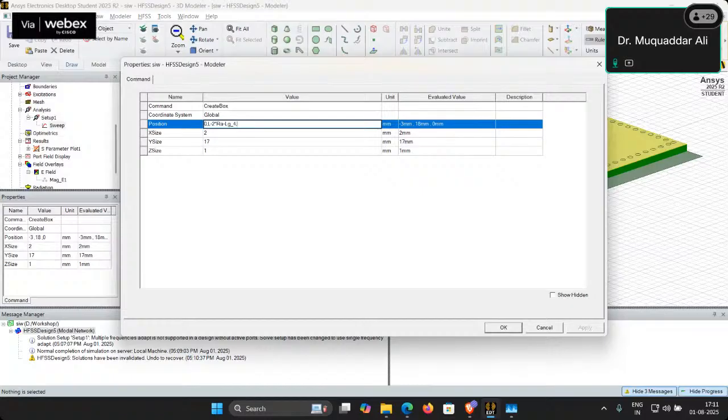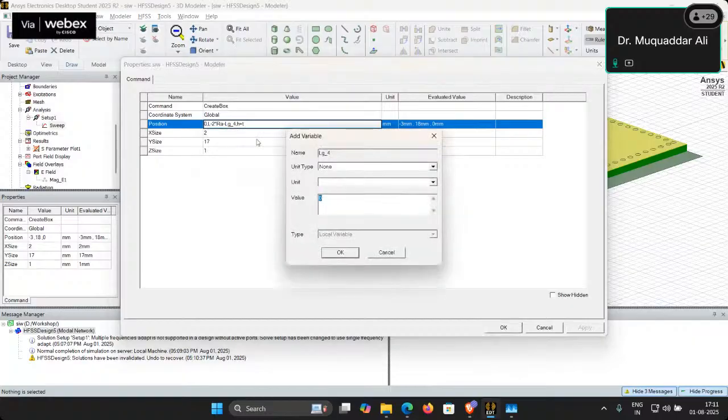And we want to cut the slot on the top of the waveguide. So on top of the waveguide, we can create this. We will be having height h plus t. It should start from h plus t, and LG4, I am giving it randomly some value, 8 mm.